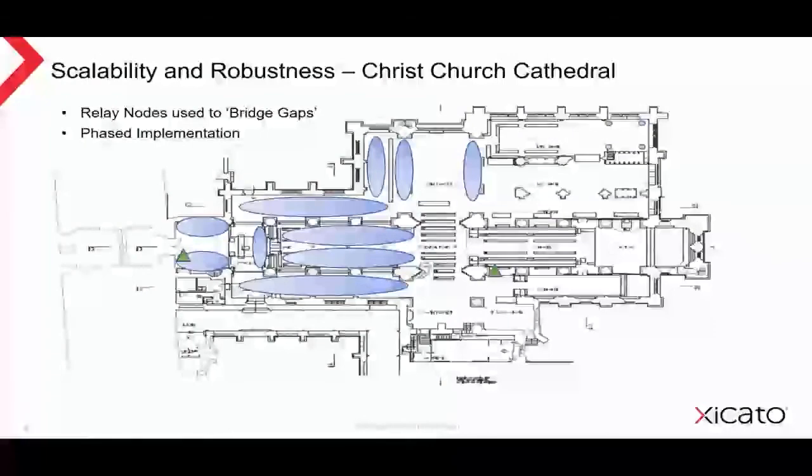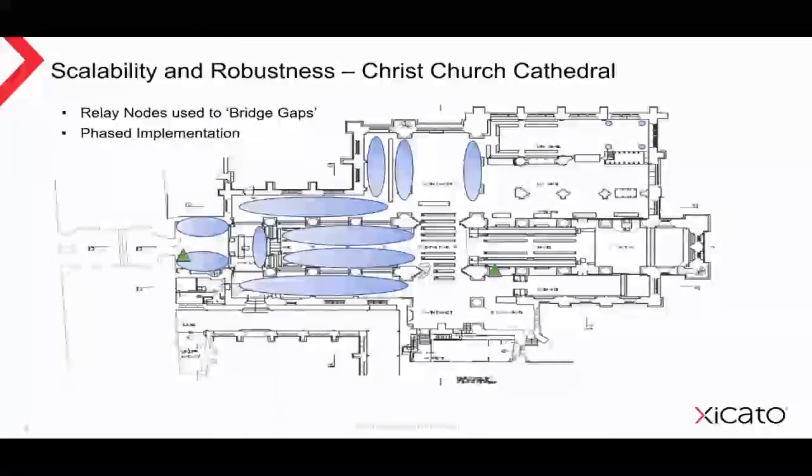So having said this, look at the switch positions. These are shown by the green triangles. One at the main entrance and a second in the AV control booth. Distances between the nearest switch and the more extreme lighting node locations are in excess of 40 meters and without direct line of sight. Any radio signal will therefore be decreased due to the attenuation caused by walls and other barriers.